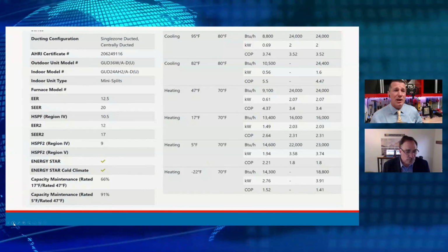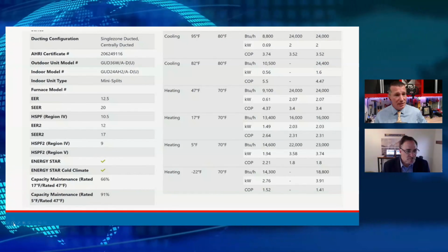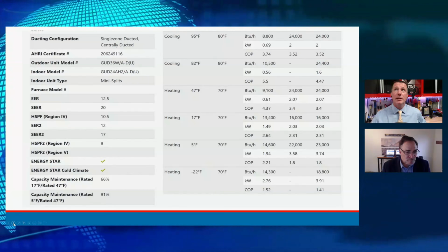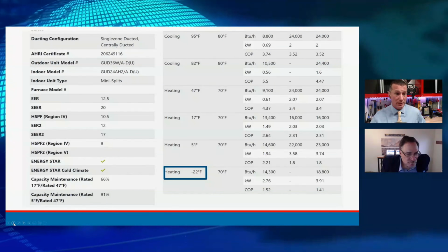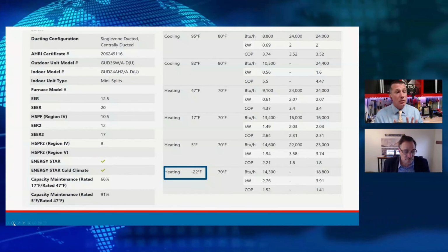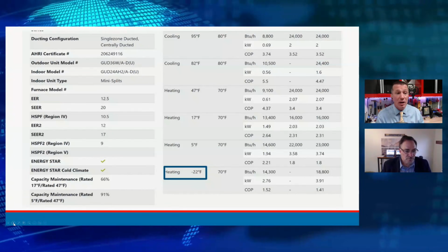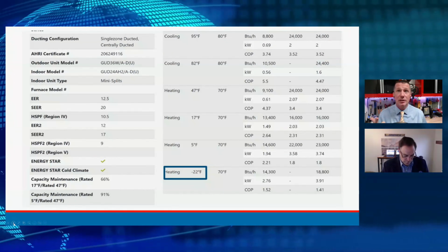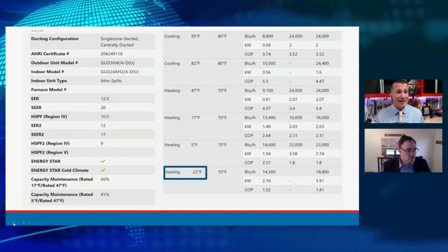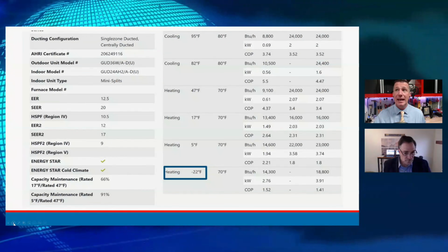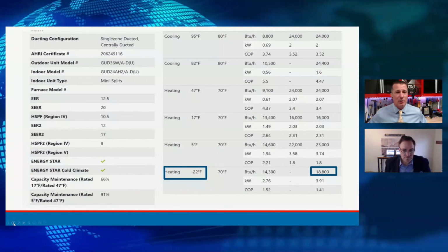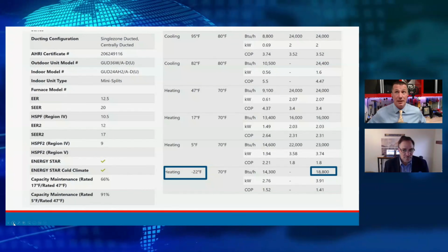Well, let's look at some of these other products in that same 3-ton range. So this is another ducted, centralized heat pump that has the capability of going all the way down to minus 22. That's why I say that if you use a tool like this NEEP database, you're also going to want to use your installation manuals or your product data to verify, because this particular one does show us, in this NEEP database, that this piece of equipment will operate down to minus 22 Fahrenheit, and in that process, it will produce 18,800 BTUs per hour of heat. That's a lot of heat.